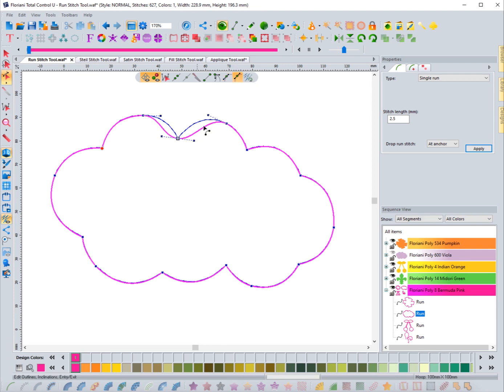If I do symmetrical, it's going to have the same distance on these handlebars. If I click and drag one, it drags the other one, so it keeps it very symmetrical. I can make it a line by right-clicking and hitting line right here, and that just makes it a straight point. That's why I don't have any handlebars right there to drag, because it's actually a straight point.